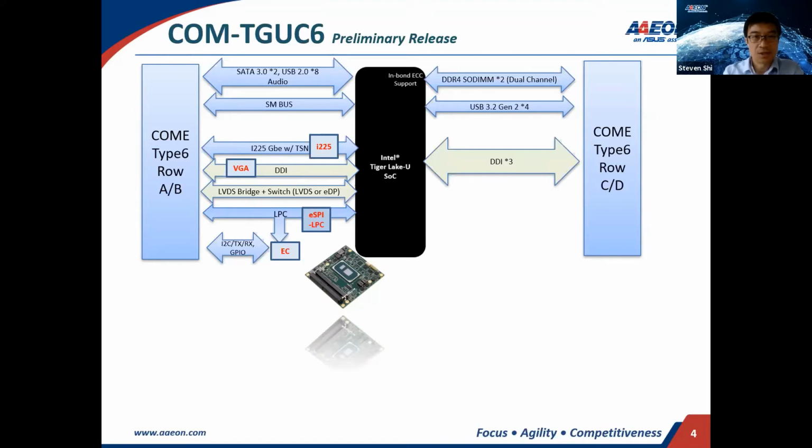And for the internal display, we have both LVDS signal and also eDP, which can support different types of panels. And for the external display, we have 3 DDI signals reserved for digital video output as well. Of course, the module itself has the UEFI BIOS and also has the TPM module integrated on this module.